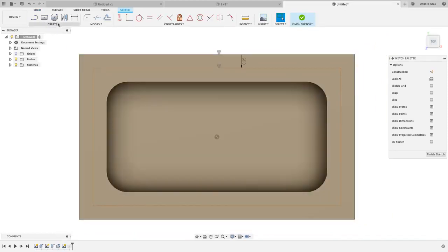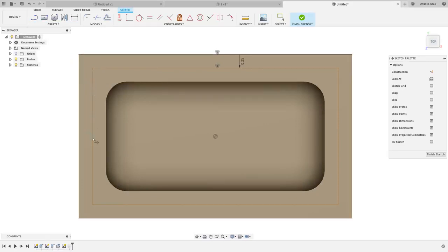What I want to do is add a couple of points. I'm going to add a point here, and as you can see, as I hover my mouse, it's snapping there on the line, and as I get to the center, it's giving that triangle symbol. That's the midpoint of this vertical line. That's the end point of the line. So I'll put a point there. I'll come to the midpoint here. We'll put a point here. We'll put a point there, and then we'll put another one. Verify we have that triangle. So now we've got 4 points that we've added.